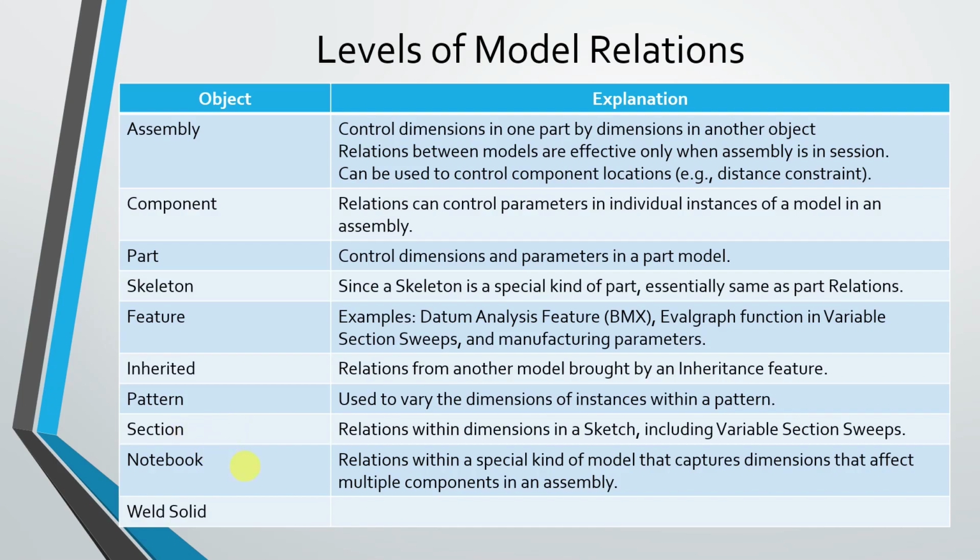Another big use, notebooks. And this goes back to when I was talking about assemblies. Assembly level relations are only effective when the assembly is in session. So if you have a part dimension being driven by an assembly level relation, it can have different values when you have the part open versus when you have the assembly open, and that's not good. So notebooks solve that problem.